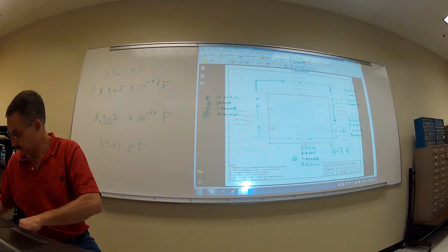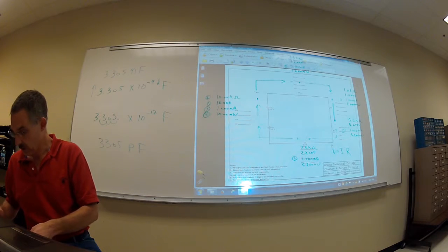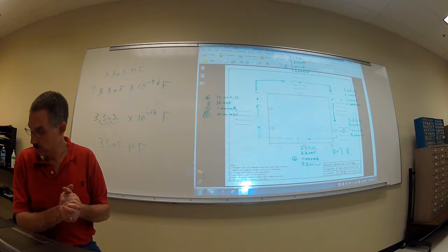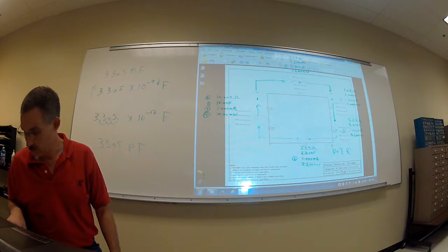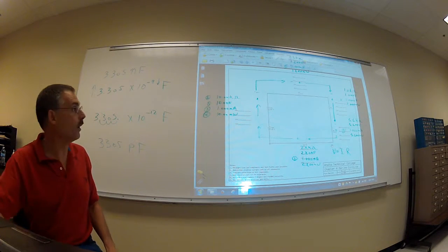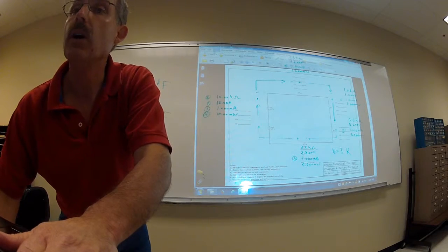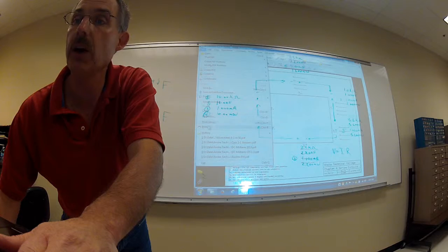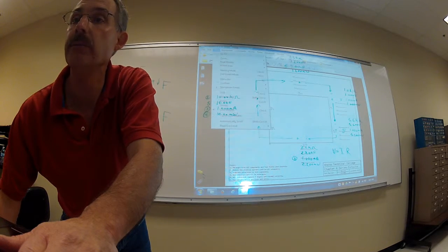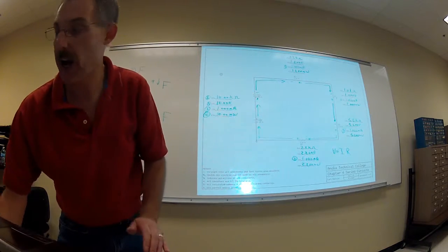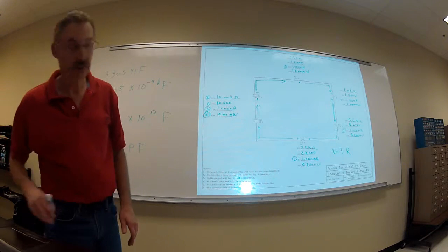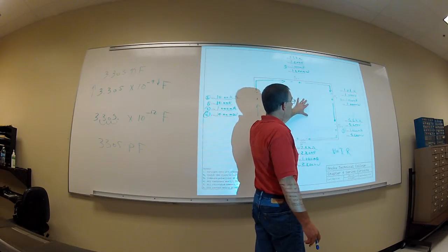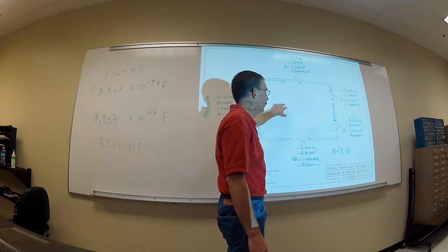This is one of our most common formulas other than Ohm's law and the power formula. This is our next one that we use all the time. We're always building up voltage dividers. And remember I said that typically when we're troubleshooting, we're going to be troubleshooting with a voltmeter.